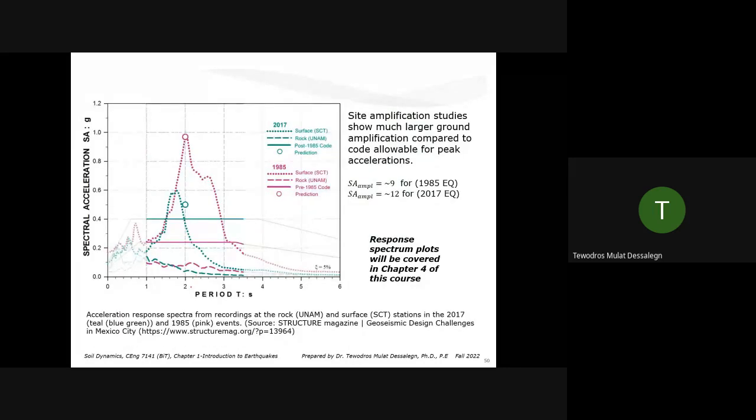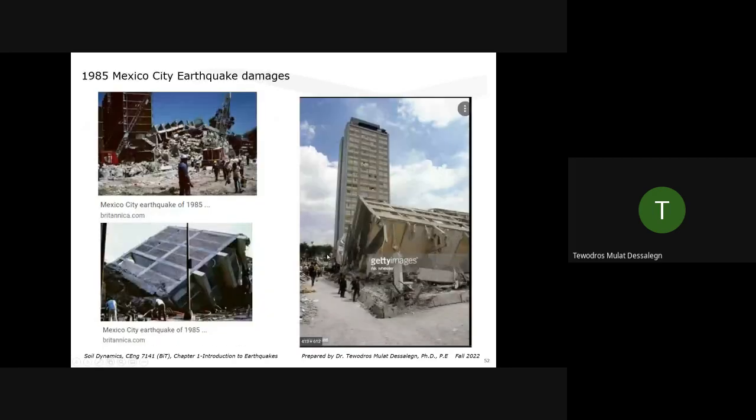That 2 seconds is this. If you see it in the earthquake response spectra, at around 2 seconds is where the maximum amplification occurred. So if you have a period of 2 seconds, that's when the most damage occurs. So this is just a perfect example. A shorter building got collapsed and destroyed, but a taller one survived it, with just minor damage, like windows or minor cracks.